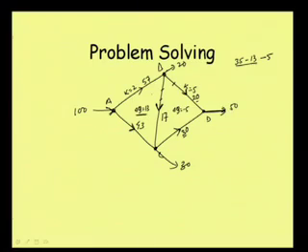We can use a variable K value or the roughness value. Then every time we need to calculate the Reynolds number and indirectly check that value. But here, for a simple situation, we are considering K to be constant, and that way we can repeat the procedure and see whether our summation of head loss is satisfied.